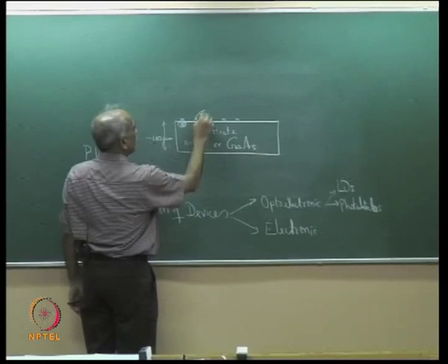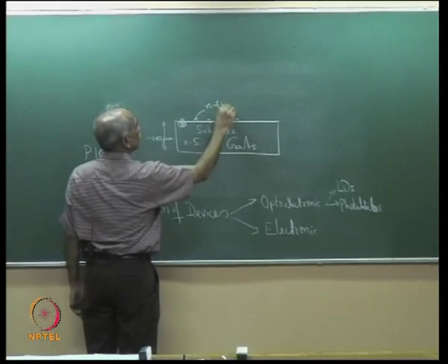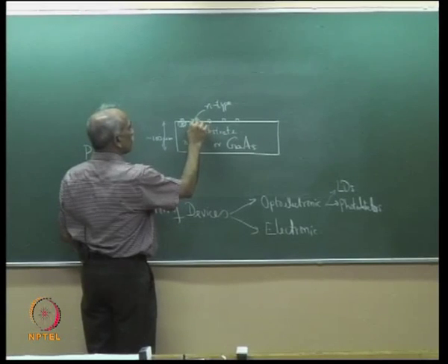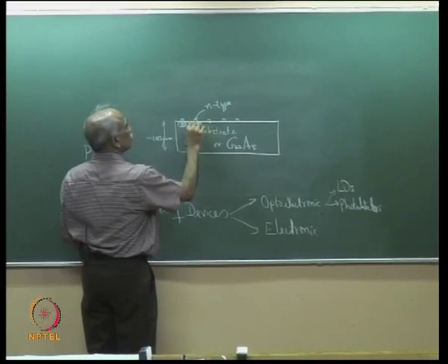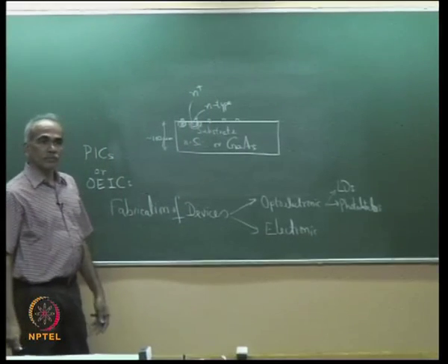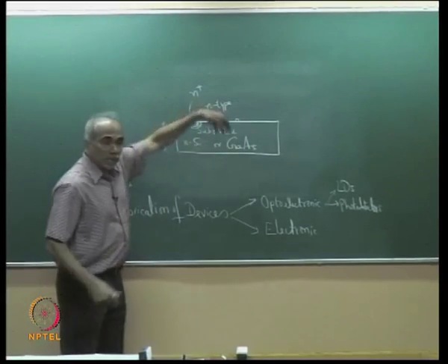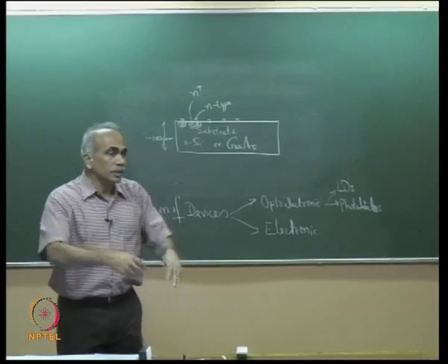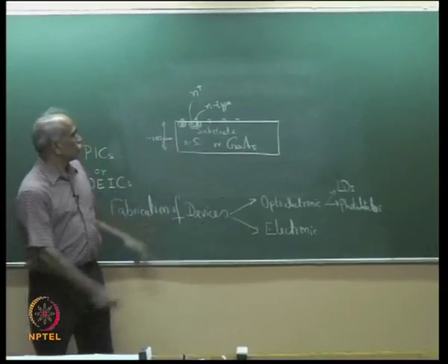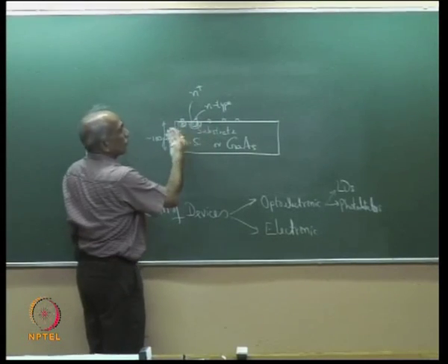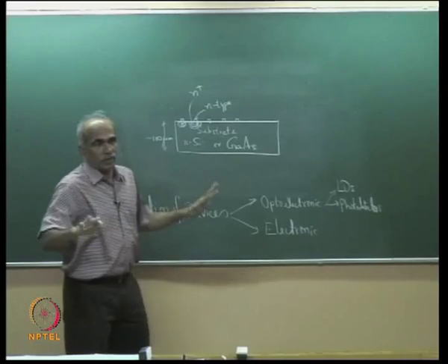You deposit an n-type dopant here and diffuse it, so you have a strong, let us say, n plus. So this diffused region is n plus. You can have any number on the substrate, on the surface, you deposit and diffuse. So you already have a p-type, n-type. So you can make NPN transistors or whatever.